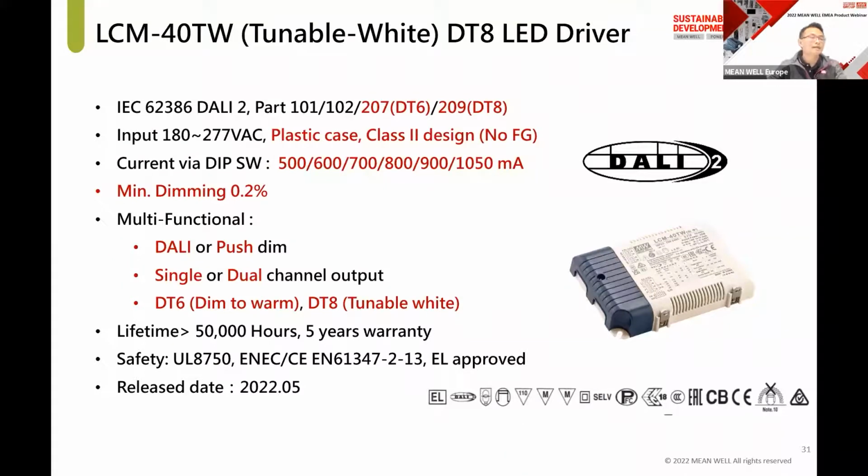Next is LCM 40 TW. TW means it supports Tunable-White. It maintains all LCM shape and functions, for example, the dip switch and the push dim function. Furthermore, it supports the DALI DT6 and DT8 functions.